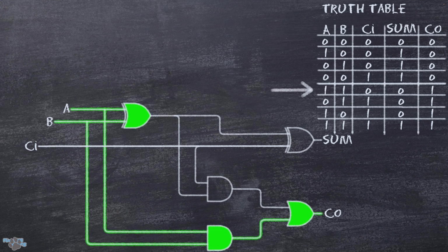When we supply 2 bits either to A and B, or A and carry in, or B and carry in, only carry out will get a bit. And finally, if I supply all inputs a bit, both sum and carry out will get an output. And as we know, 1+1+1 is equal to 3, which is how many bits I gave it.